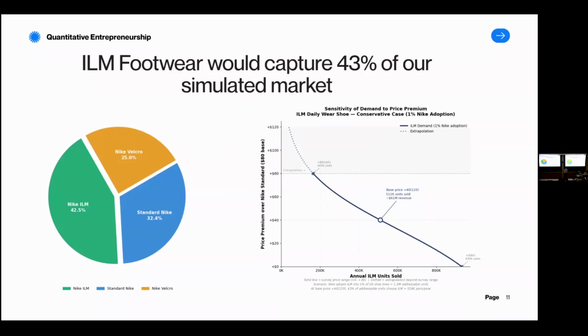Yeah, so ILMs are based around the idea that they're highly customizable. They consist of a unit cell that could be designed for a specific purpose, and then they're patterned over an array that can also be tiled in a way to achieve different strengths. The conventional designs we have don't really deal with shear strength in that way, but that is actually one of the topics we're looking into in our lab. So that is hopefully something that we would be able to achieve. But of course, that depends on the manufacturing and everything like that.